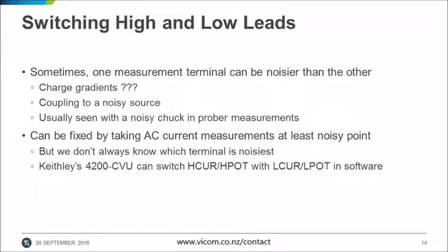Occasionally, even after trying everything to make a crucial CV measurement, the signal is still noisy. We're using 4-wire connections, we performed open, short, and load compensation, and we have our device under test shielded with an aluminum sheet. What more can we try?